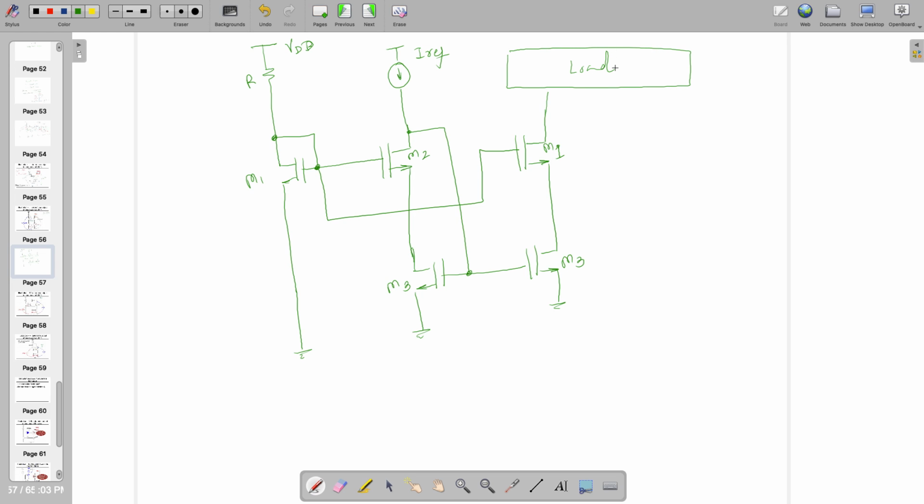So here I have determined that if I want a good current source which has two characteristics, source impedance infinity and V minimum as 0, we learned that the better technique in terms of source impedance is actually Cascode. However, we are losing in terms of V minimum.